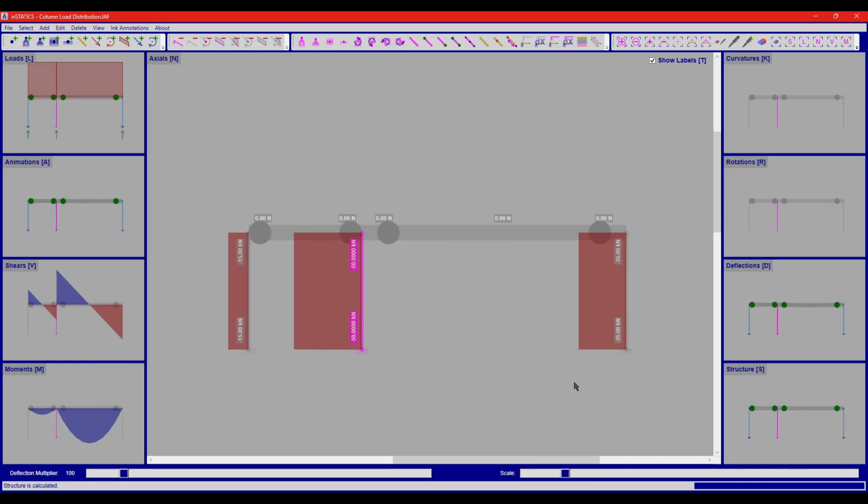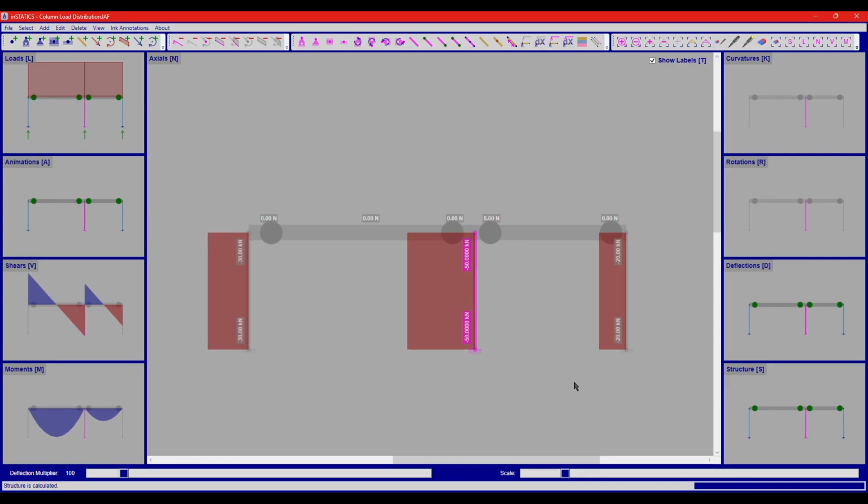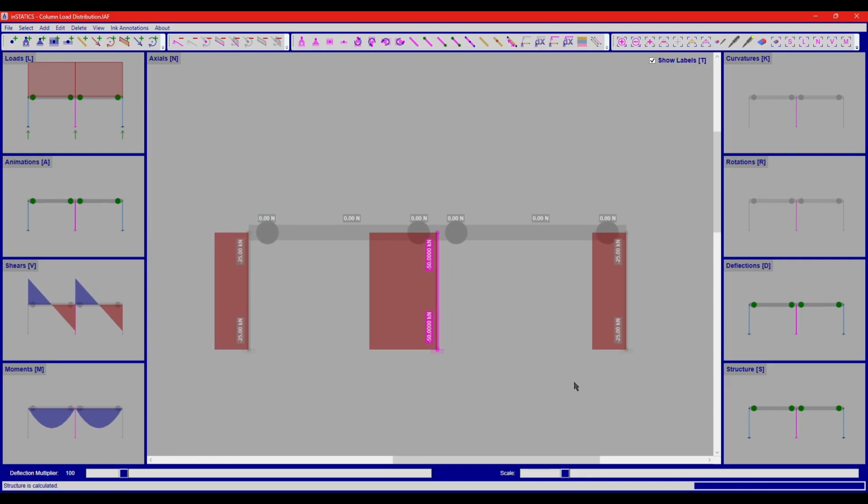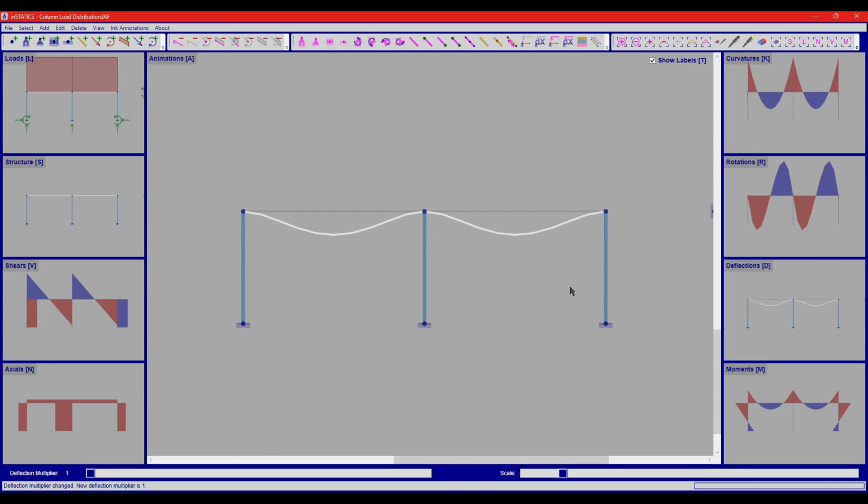Surprisingly, when the inside columns move, their load does not change since they will still end up carrying half the total load. The load distribution is more complex when the span is continuous. This makes the structure indeterminate, and distribution of the load will depend on the relative stiffness of the elements.